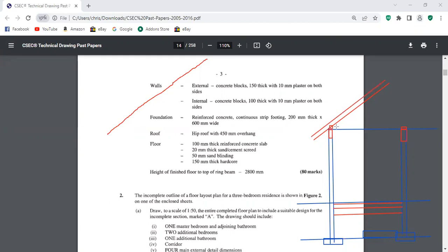We would then draw, you could use X line. You could use X line, XL vertical, and drop a vertical line right here, and then offset it. Or you could draw a line here, 450, then go up. So this can be done one of two ways. I like to use XL. I use that XL vertical, and I would then click here, and XL would produce a straight line here.